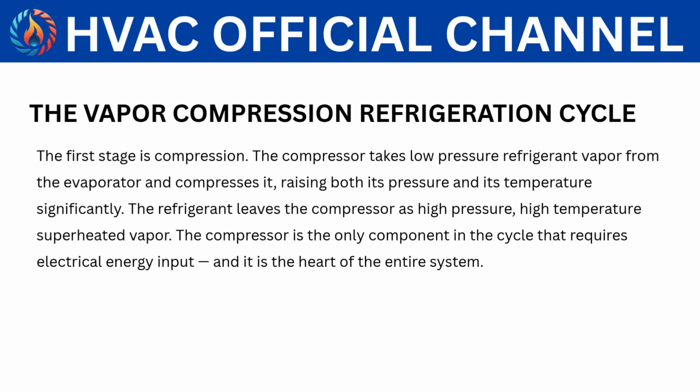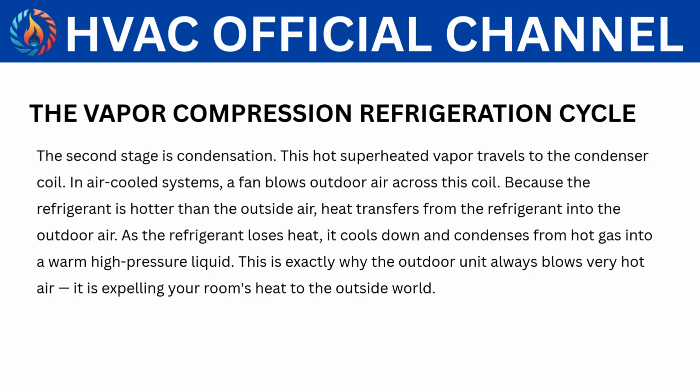The compressor takes low-pressure refrigerant vapor from the evaporator and compresses it, raising both its pressure and its temperature significantly. The refrigerant leaves the compressor as high-pressure, high-temperature superheated vapor. The compressor is the only component in the cycle that requires electrical energy input, and it is the heart of the entire system. The second stage is condensation.